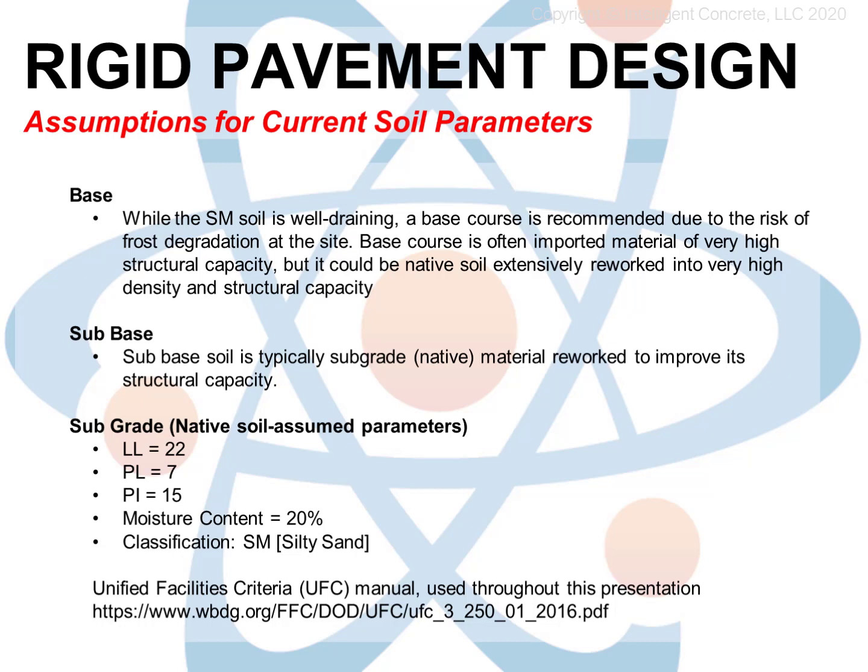Remember how we just talked about this with the Atterberg test and how a soil can turn plastic and unstable with moisture? Sometimes the base course is comprised of soil imported to the site because the native soil is not considered to have sufficiently high structural capacity. A subbase is a layer of soil that's built under the base. It's often made up of native material that is moisture conditioned, meaning water is added or water is allowed to evaporate, and then recompacted in thin layers, usually about 6 or 8 inches thick each, but usually at a lower density than the upper base course layer.